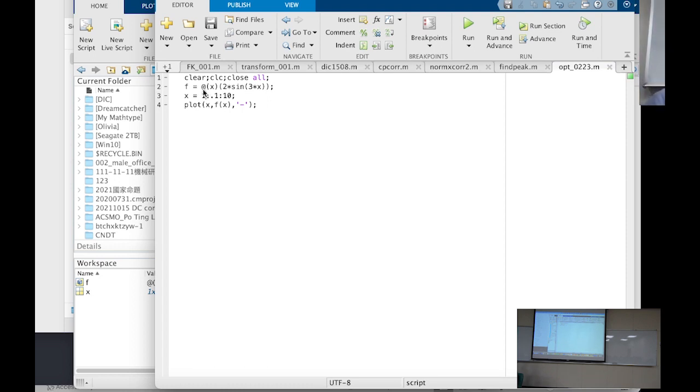There's a way of defining a function by so-called handles. So if you write the at sign, some variables inside brackets, followed by another bracket indicating your function, the function needs to have the component of the variable. So there's an x right here. So it's very easy to use later on when you plug in numbers. Now I define another variable.